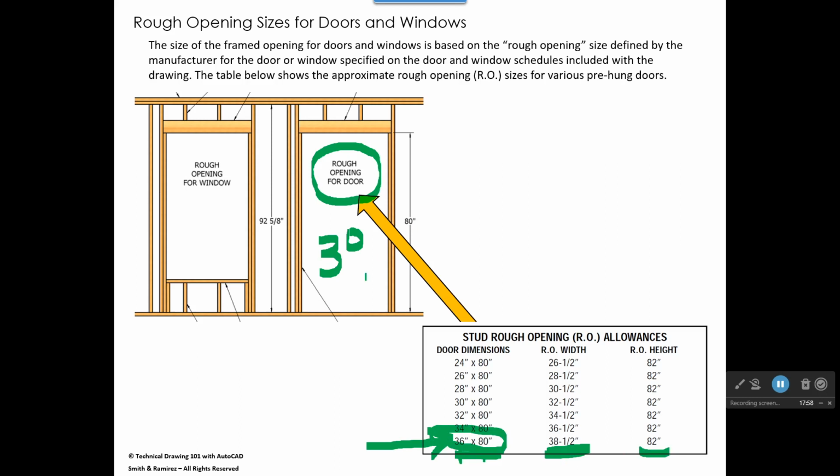Now, if you're doing a commercial building and your windows and doors are all set in metal frames and they can be built at a factory and be pretty precise, what I'm telling you may not hold. They may actually be able to dimension from side of a window to the side of a window because it's a lot more accurate than framing with lumber, right?